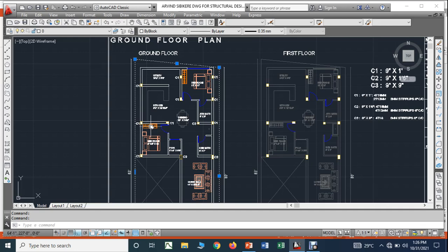Not only that, students, when I say that my building should not go beyond this boundary, it means even your foundations should not go or exceed these lines. You have to decide the positions of the columns in such a way that when you excavate and put the footings, they should not go beyond these lines, whatever I have selected.